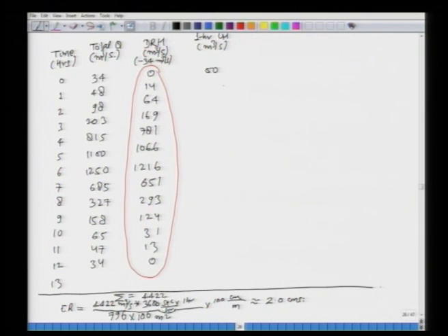So, you will have 0, 07, 32, 85, 391, 533, 608, 326, 147, 62, 16, 07, 00. So, what I have obtained is the 1 hour unit hydrograph given the data, and this is the same procedure we had seen in the last class for a similar example.